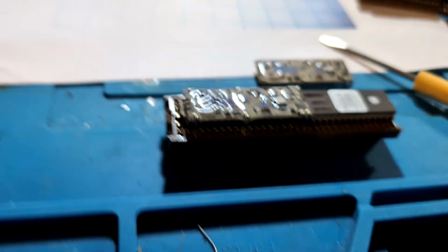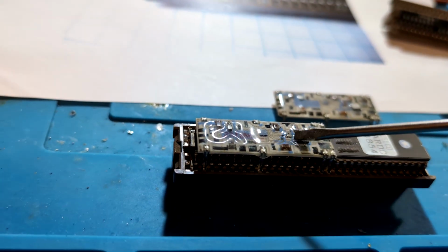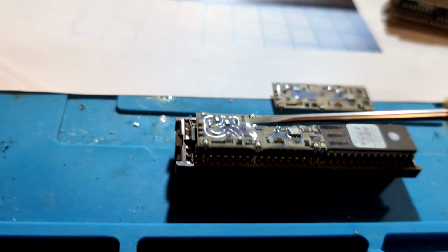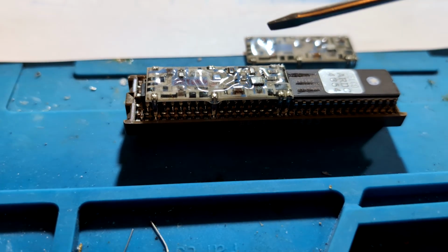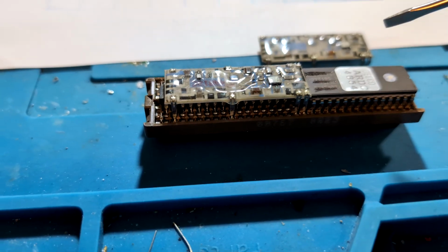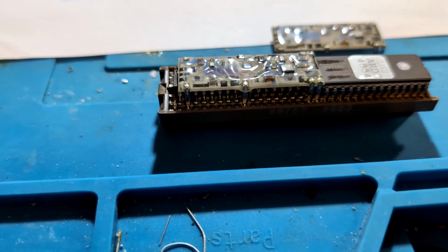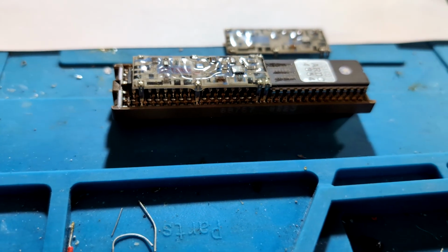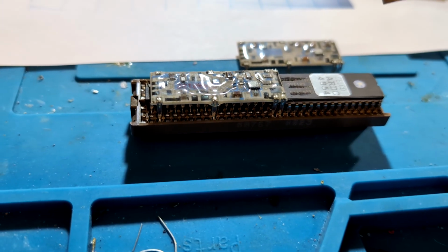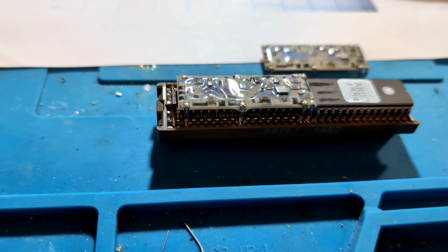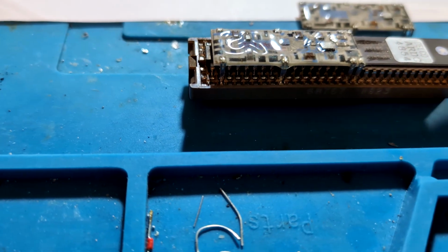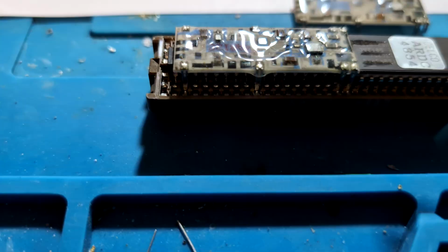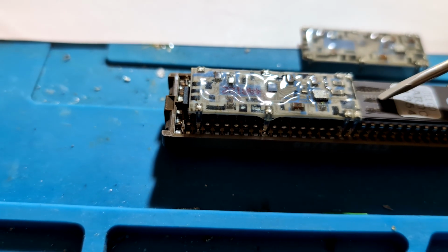What I have done in the past is desoldered this, removed it completely, and then turned off all knock control in the program using Tuner Pro, and I've run that without any issues whatsoever for many years and many miles. So in order to do it that way, you can use a V6 or a 4-cylinder Memcal.